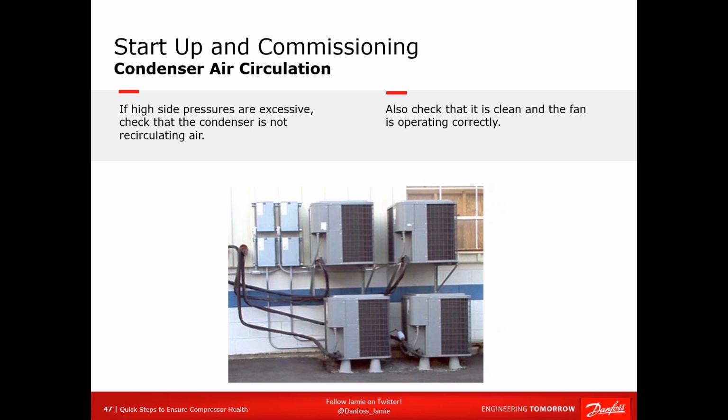Finally, make sure the condenser has good airflow. It is getting outside air and not regurgitated air from another condenser or an exhaust outlet from a factory, whatever. Condensers are dumb. They don't know what the outside temperature is. All they know is the temperature of the air that's going into them. So if you're rejecting air out of a condenser at 110 degrees on a 90-degree day, and it enters into the outside upstream condenser, the condenser is going to act like it's 110 degrees outside, and it's going to burn a lot more energy.